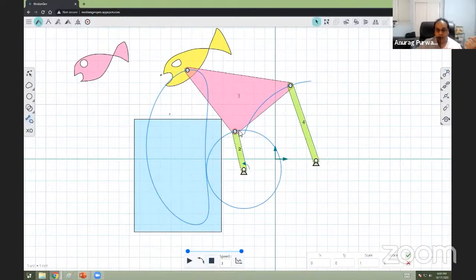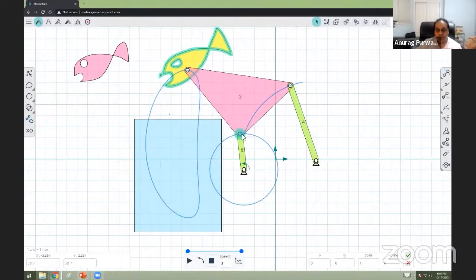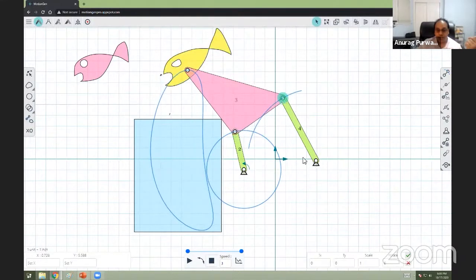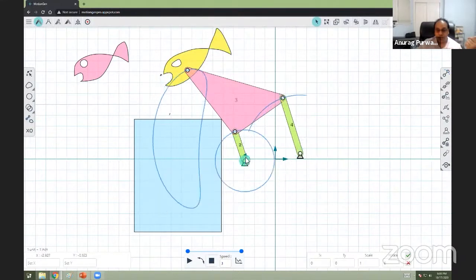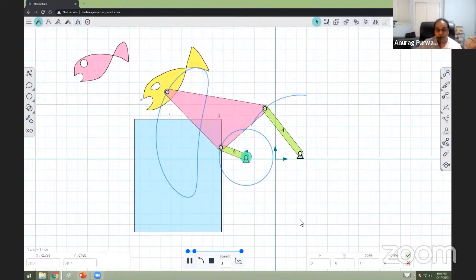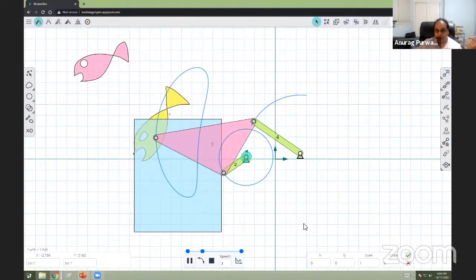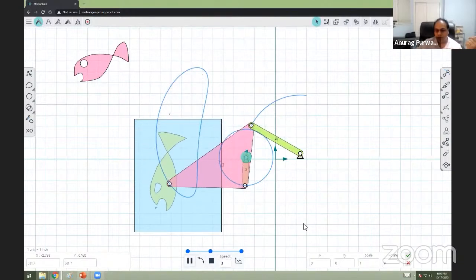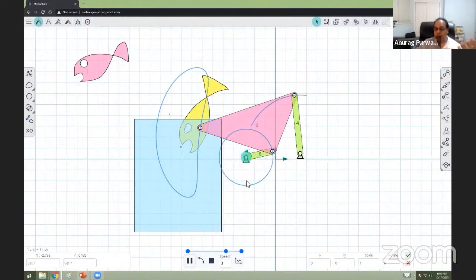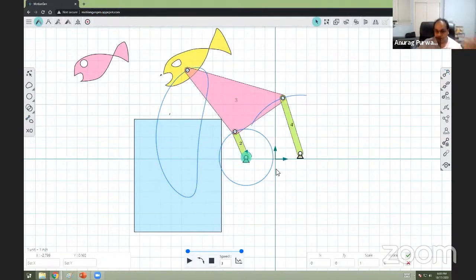So what I can do is change these parameters, right? I can move these, and I can see in real time how these paths are changing. As I move these pivots, or as I change the link length, I begin to see newer motions, or newer motion curves, appearing. So this looks kind of like what I might like to do, right? So imagine trying to design a robot or a machine that basically does this for you, okay?